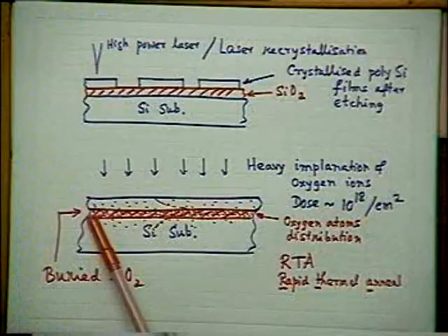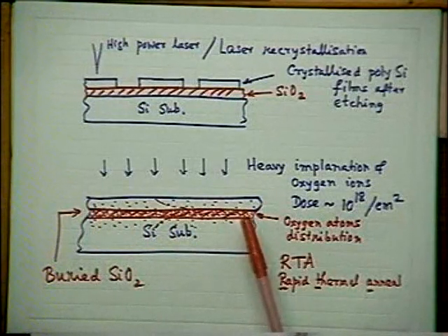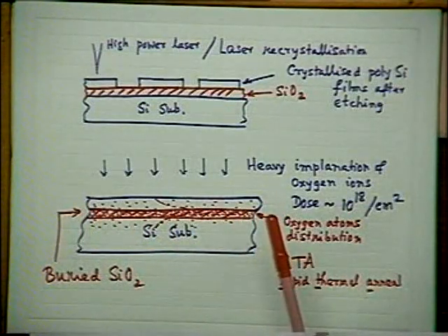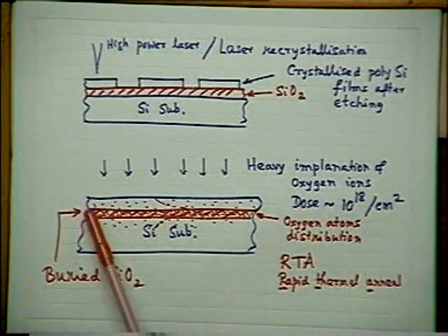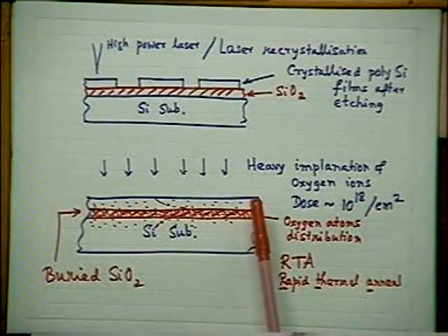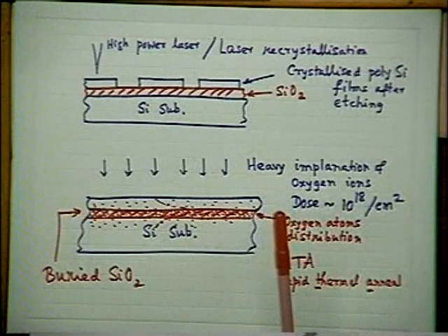And after annealing, after the rapid thermal anneal, not only does the silicon dioxide formation become very proper, but the film on the top also recovers greatly from the damaged condition. It becomes a very good crystal. Its mobility is recovered. Annealing recovers not only the damage, but electrical properties are also recovered.